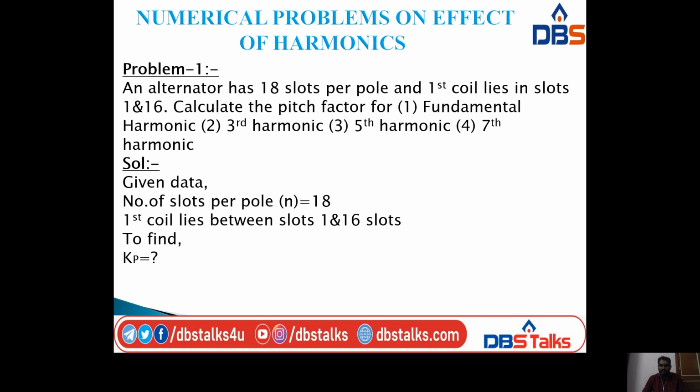The first problem is: an alternator has 18 slots per pole and the first coil lies in slots 1 and 16. Calculate the pitch factor for the fundamental harmonic, third harmonic, fifth harmonic, and seventh harmonic.